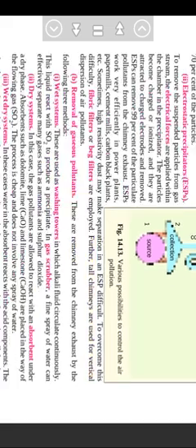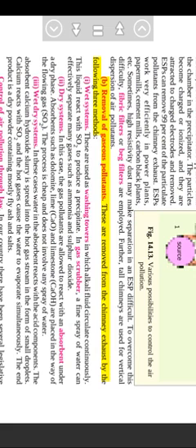B. Removal of gaseous pollutants. These are removed from the chimney exhaust by the following 3 methods. 1. Wet systems. These are used as washing towers in which alkali fluids circulate continuously. This liquid reacts with the gas to produce a precipitate. In a gas scrubber, a fine spray of water can effectively separate many gases such as ammonia and sulfur dioxide. 2. Dry systems. In this case, the gas pollutants are allowed to react with an absorbent under a dry phase. Absorbents such as dolomite, lime, and limestone are placed in the way of the flowing gas. The process is cheap and does not involve any spray of water.